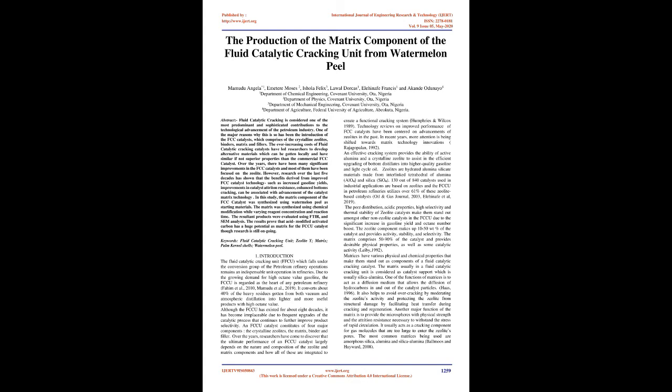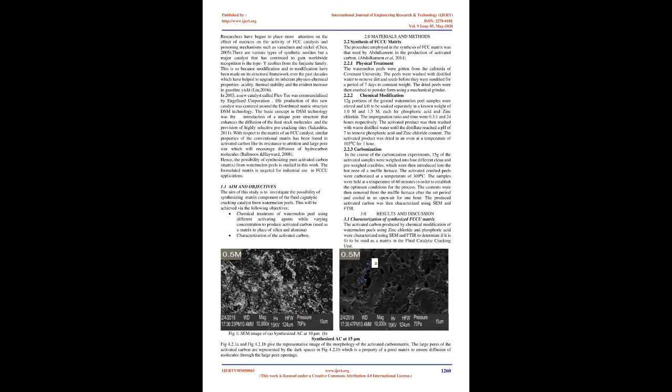Technology reviews on improved performance of FCC catalysts have been centered on advancements of zeolites in the past. In recent years, more attention is being shifted towards matrix technology innovations (Rajagopalan, 1992). An effective cracking system provides the ability of active alumina and a crystalline zeolite to assist in the efficient upgrading of bottom distillates into higher quality gasoline and light cycle oil.